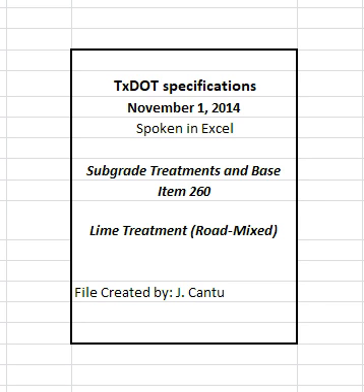Where subgrade to be treated under this contract has sulfates greater than 7,000 ppm, work will be paid for in accordance with Article 4.4, Changes in the Work. Asphalt used solely for curing will not be paid for directly but will be subsidiary to this Item. Asphalt placed for curing and priming will be paid for under Item 310, Prime Coat.